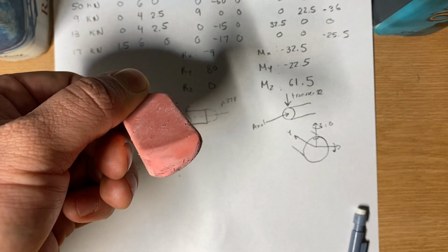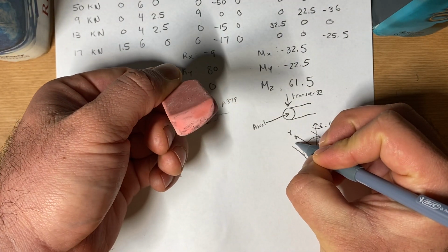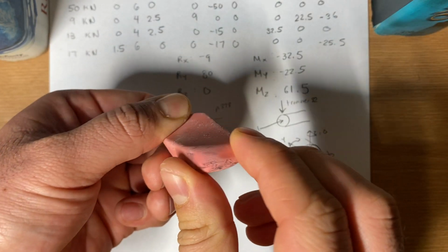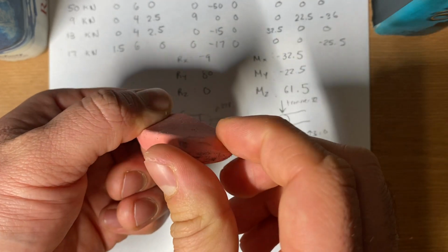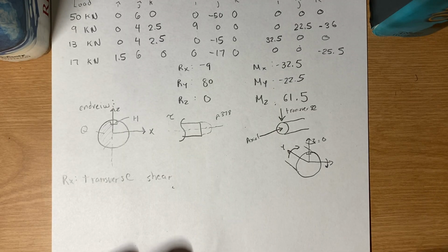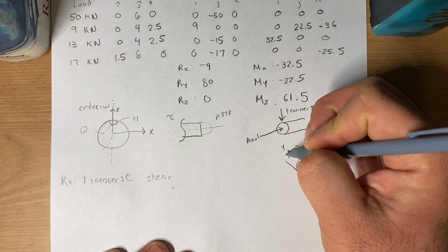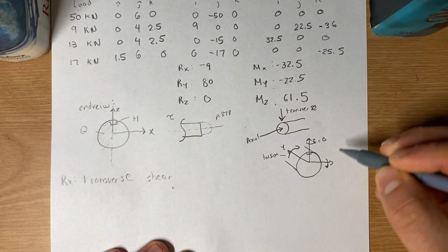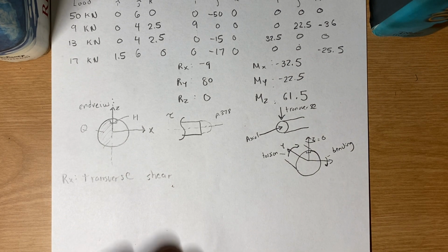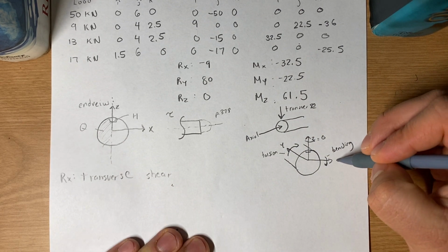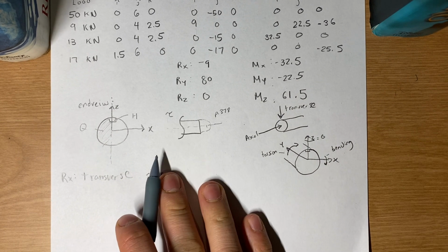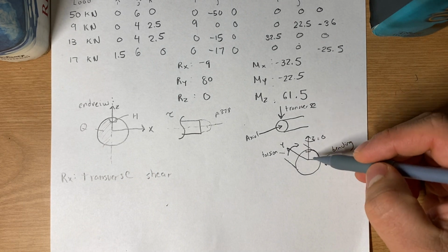So if I have my Y right here and it's going this way, then I know this is going to cause shear. It's going to cause torsion, so it's going to look like this. This is torsion. So here at my Y, I know there's going to be torsion, and then here, this one, I know there's going to be bending. So this is my X. So I know at my RX, my reaction, there is a transverse shear